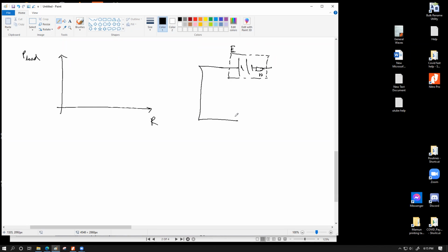If we connect this to, let's say, a variable resistor and have a circuit, obviously we're going to need the ammeter, and we're also going to need the terminal voltage measurement. If you slowly start to change the value of the variable resistor and take pair values of A and V, the product of these two readings will give you the actual output power, because this is the current, this is the resistor voltage, so power equals V into I. You will also know the resistance of this resistor because you choose that number. So practically this power gives you the load power, because the terminal voltage into current gives you the load power.